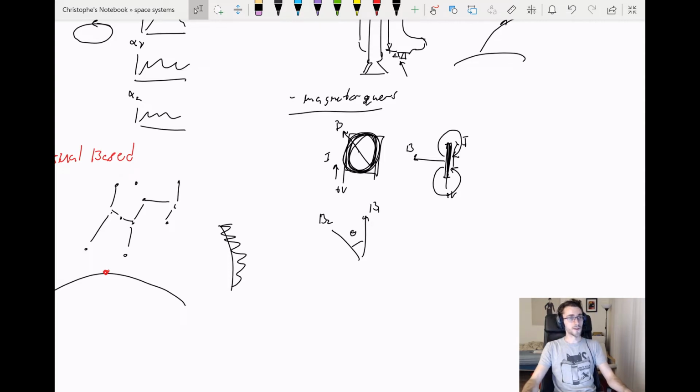What magnetorquers do is you can just flip them on and wait, because they apply a stabilizing torque to your craft. If you're spinning erratically, over time it'll start to slow down to the point where you can say, okay, magnetorquers off, active control systems on.